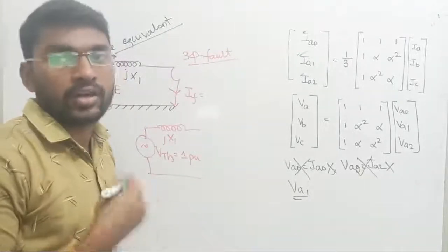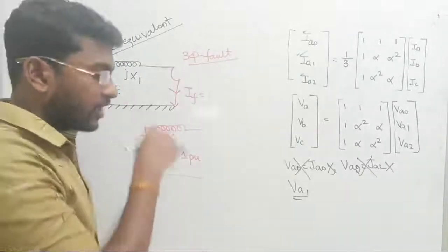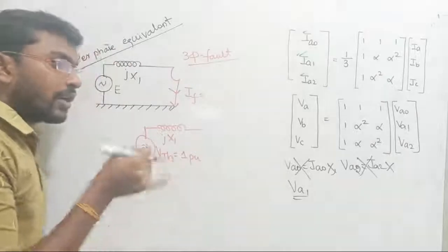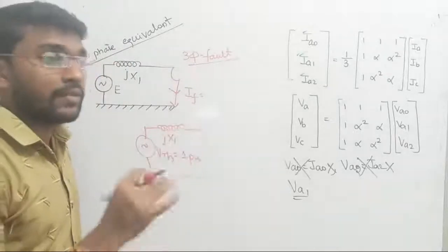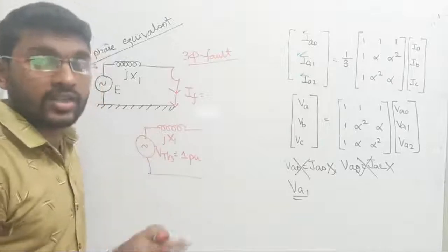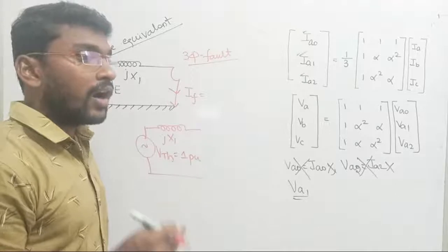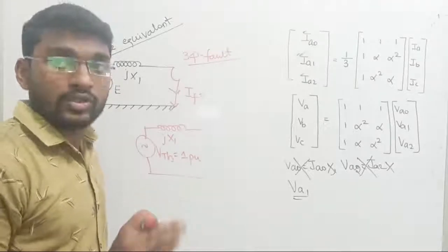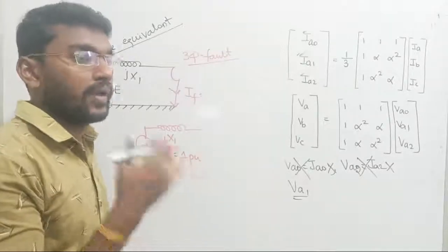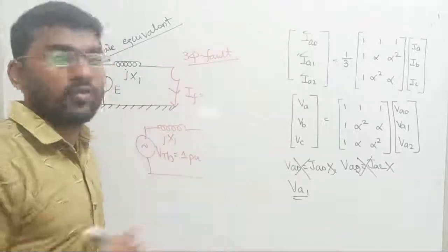Prior to the fault, what is the voltage, right? Starting itself I have concluded, prior to the fault, right? Actually, our assumption is that a fraction of a second before the fault happens there were no loads. No load was connected to our system at all, that is our worst case analysis. Why? If you fix in your mind that no load is connected, then before the fault the load would not have consumed any current. So the power transfer between the source and the load is going to be zero, such that maximum current will be diverted to the fault line.